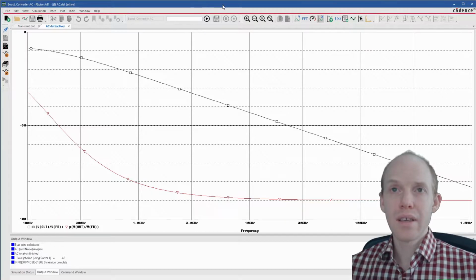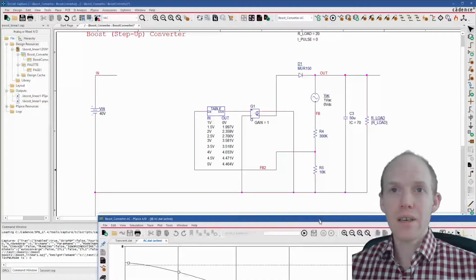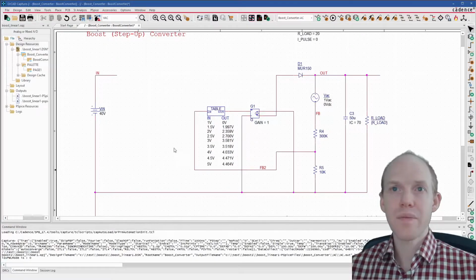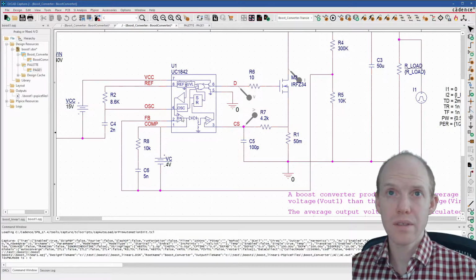And what you might have figured out already here is that the main reason is because we've kind of thrown out our controller. See, we got rid of this whole control chip right here, which along with the reference and this compensation that we put in. So we linearized it right here at the output, but we need to add this op amp back in with the reference and this little network here.